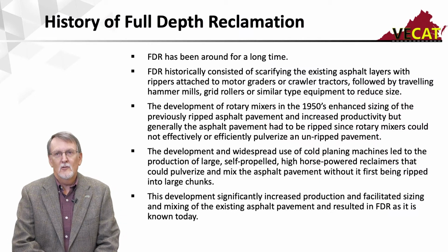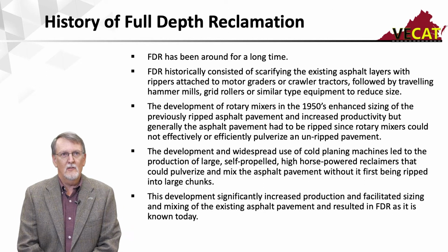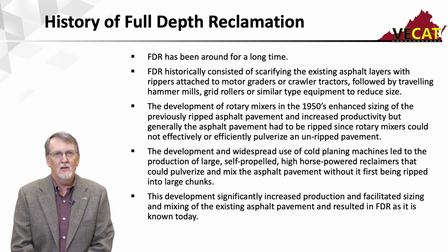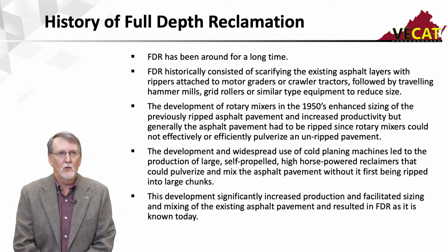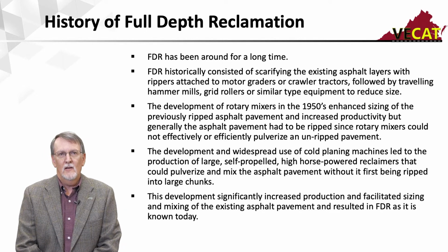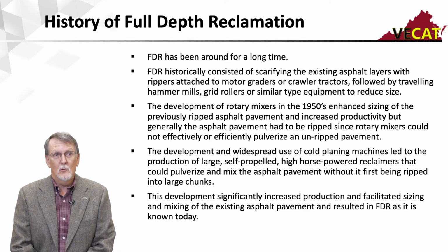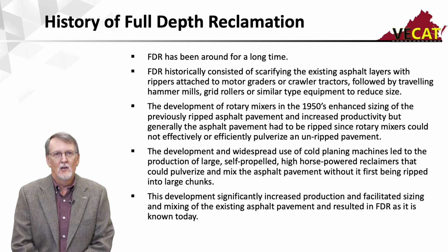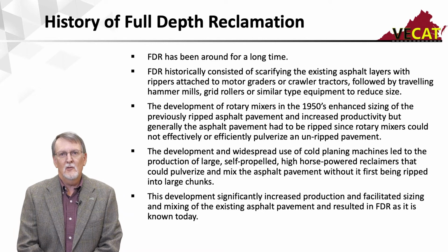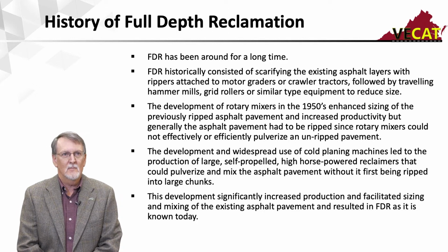So a little bit of history. It's been around for a long time. And when it was first started, they would take the scarifying tines on the back of a motor patrol or use rippers attached to motor graders, and they would run it down the road and just rip up the pavement. That resulted in large chunks. So they would have to take hammer mills or grid rollers and run those over to bust the material up into smaller size so they could get it adequately compacted.